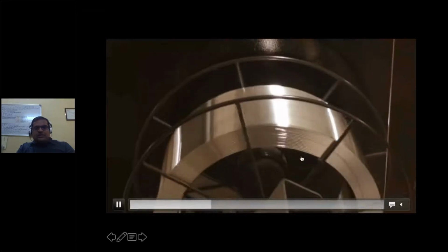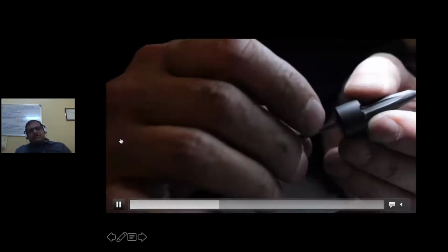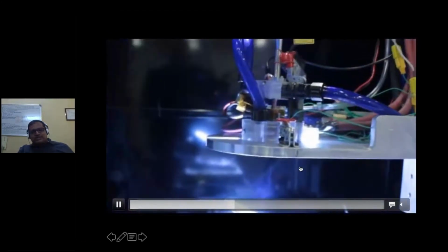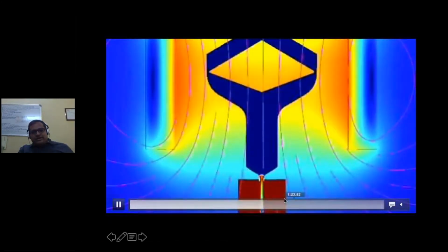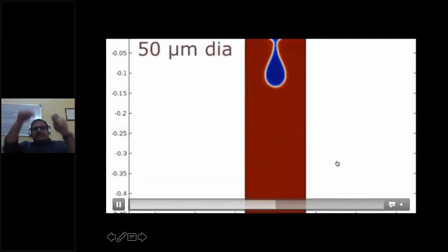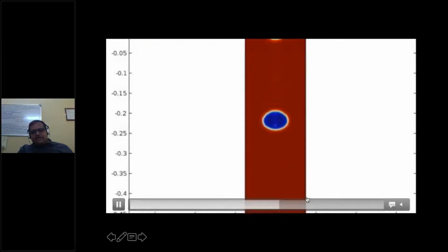the laser based powder bed systems. So now people are able to jet this molten metal, taking raw material in wire form, either aluminum or any metal. So this will be very easy, right? You melt it, and then you pass it through this nozzle and you spray it. So this molten metal will be sprayed, and of course you need to have a harder nozzle, maybe ceramic or some harder material. So then it will be jetting from that, right? So this molten metal will be jetting from it.